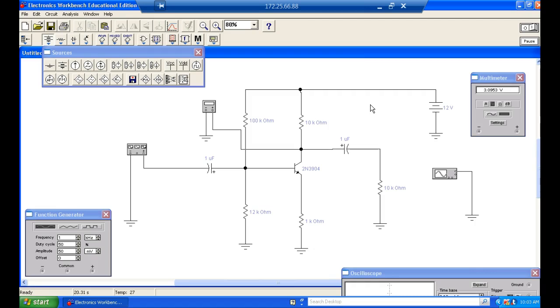And how could you check that? You could check this in circuit. It's just like shorted capacitors. We can check this in circuit. Put my ohm meter up there. We don't need to pull one leg. It's going to measure, well, yes, but it's going to measure 0 ohms. We okay? But you're right. Once we measure 0 ohms, we pull it up, it still would measure 0.